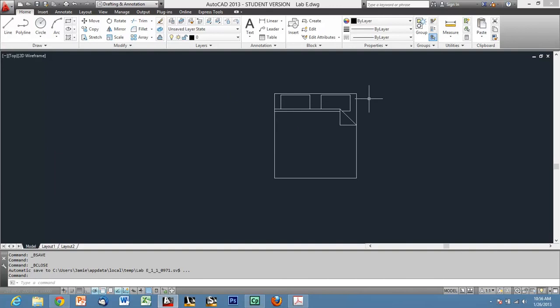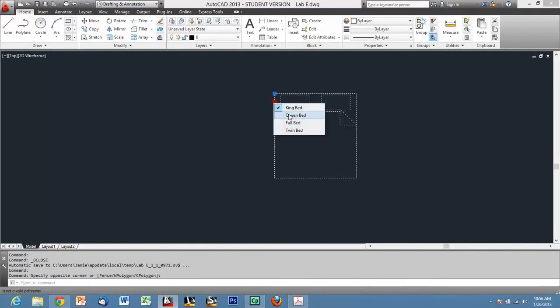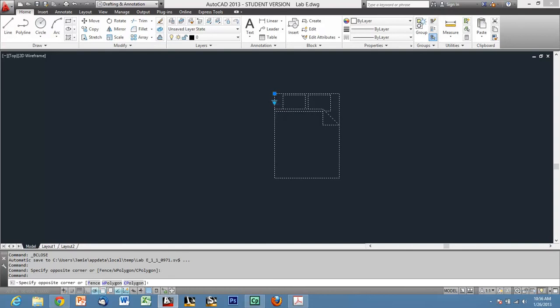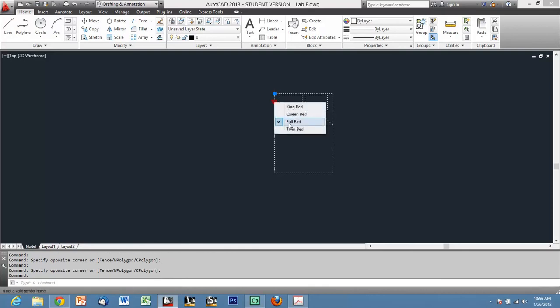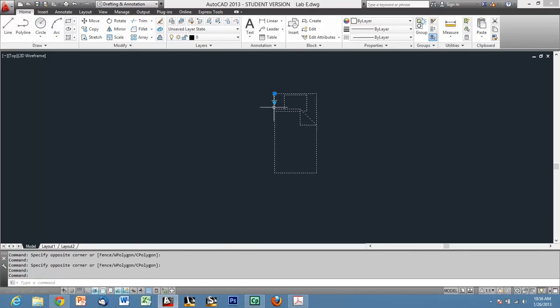So now at this point, back in regular old AutoCAD, we have created a dynamic block for these four different mattress sizes. So if you were laying out, say, a 3-bedroom house and you wanted to have different mattress sizes, you wouldn't have to redraw them constantly, or if you're trying to figure out if one may fit instead of another. You can go through and seamlessly change those without having to spend time drawing them and checking the sizes and making sure that they're right.